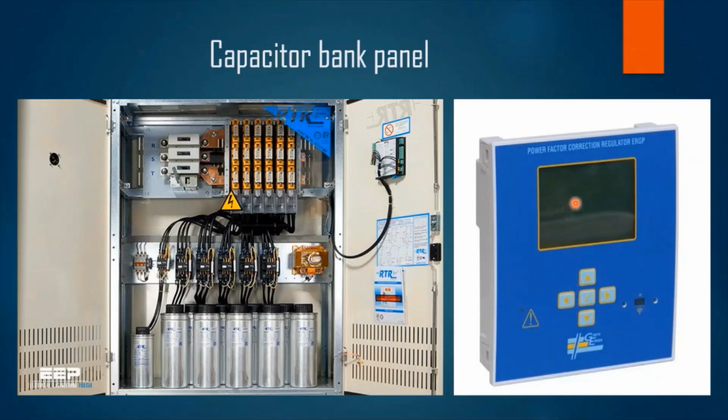So we will set a power factor correction, for example, from 0.8 to 0.95. Then according to the demand load in our system, these capacitors are going to work. This means that it's not necessary that all these capacitors should work at once. They actually work in a technique called steps. And this is because the demand load varies during the entire day.